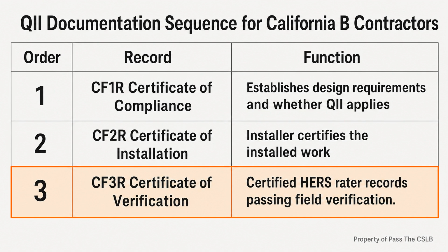Suppose a drywall crew is released because the insulation looks finished from the hallway. If the required rater has not inspected the concealed conditions, photographs and assurances do not automatically replace the prescribed field verification. Board may have to come back down, or another approved resolution may be required. The immediate mistake is not merely poor insulation, it is losing access to the evidence.